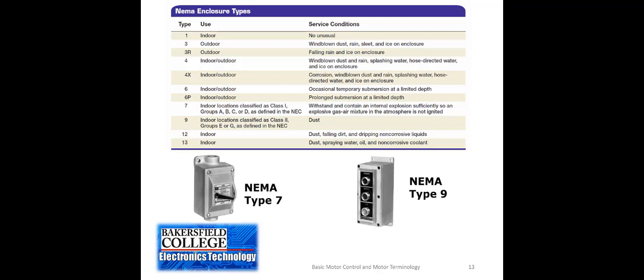And so that's one of the reasons why, when they have situations that are dangerous or hazardous, they really need to be designed by engineers that understand all of the safety factors that need to be engineered into the circuits. But if you take a look at this, you'll see that there are a number of different types of enclosures. And if you're the person that needs to replace one, then you need to replace it with the same type of enclosure that it was originally designed with.